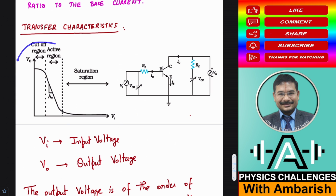Let me explain this graph in more detail. What is happening when the input voltage is very small? The base emitter junction is not properly forward biased, and when it is not properly forward biased, there is practically no current. The emitter is not giving out any current, so the collector current is 0, and if the collector current is 0, there is absolutely no drop across this RC.